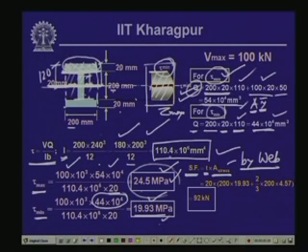Now, for the area of the stress diagram, we can divide the whole stress into two parts. The stress distribution is something like this. We can divide this into two parts, one is this rectangular part and another is this parabolic distribution. This value is tau minimum and this height h is equal to 200.